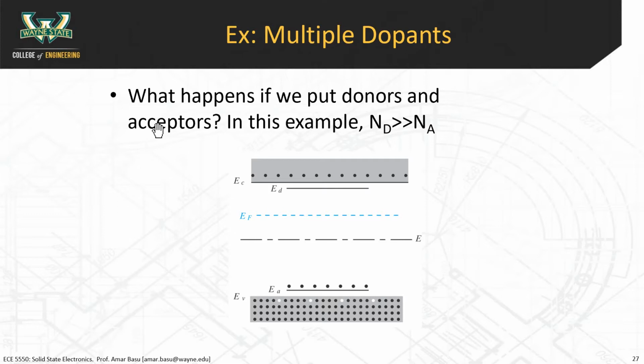Let's say you started off n-type, right? If you want to kind of erase what you did, you can put a p-type dopant in there, and now you'll have a neutral material again. You'll move that Fermi level back down to the middle. But this is if the acceptors and the donors have the same numbers of atoms. Right, exactly, if you have the exact same number.